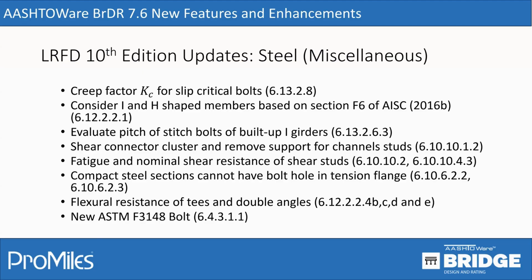Also, there were some changes for fatigue and nominal shear resistance related to shear studs. There was an update especially for straight I girder bridges, not to have compact steel sections, which should not have bolt holes in tension flanges. There were also updates for flexure resistance for T's and double angles in the spec update.